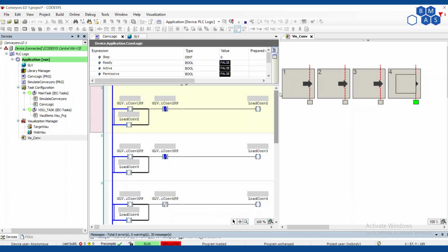In any situation where you've got conveyors, the first conveyor and last conveyor are always going to be a little different. That's absolutely true here as well. In this case, I'm assuming that a person is loading and unloading, and that's me with the clicker, obviously application dependent. So let's add another one, and that should stop at 3. Add another one, that should stop at 2. And then if we add a final one, this shouldn't go anywhere because there's nowhere for it to go.